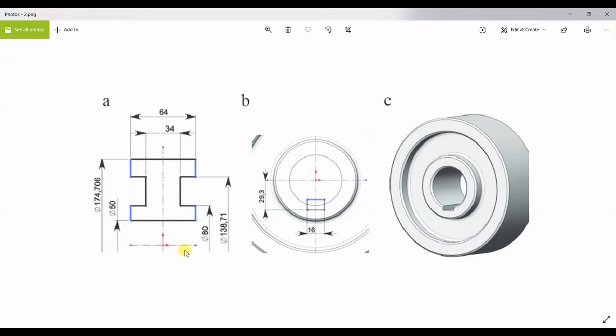Now the difference between the previous revolution commands we have seen and this particular exercise is the location of the sketch. So far we have seen the different ways of creating the revolve geometries, and whatever we were creating, we were locating or placing the sketch on the central axis. But in this particular case, the sketch or the closed loop has to be placed at some distance from the central axis. The reason for that is the hole which is seen over here.